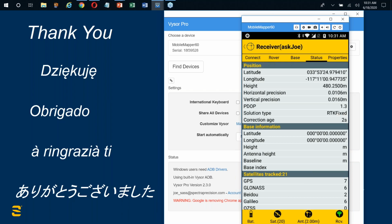Come back over here to status. You can see right now we're SBAS and now we're fixed. Within a moment or two, we should get information about our base station. That information is not broadcast as often as the RTK corrections themselves are, but before long, it should populate. Anyhow, we're in an RTK fixed solution.